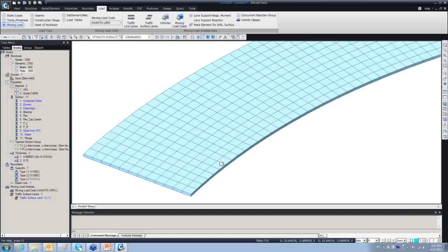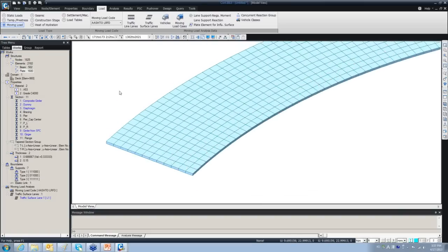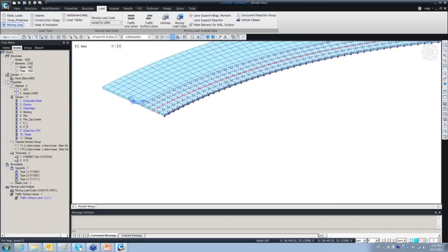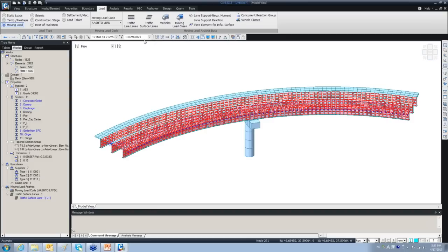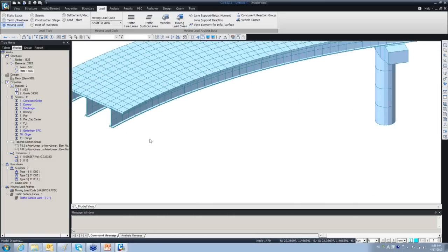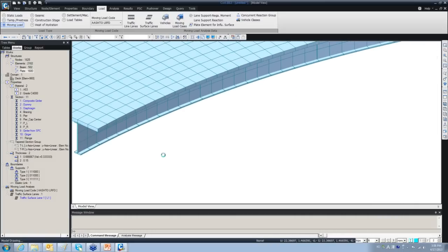So you can simply define the same lane on the other side with any eccentricity that you are interested in. Then we have to define the self weight for this, and you know the rest of the story for such elements. So let me unselect these. Yeah, and again, you have to apply those boundaries which we defined previously. Those should be applied, and that's the important point, when you do the beam plate element like this one, you don't need to define additional nodes in the bottom, because, for example, if I want to show you this corner,